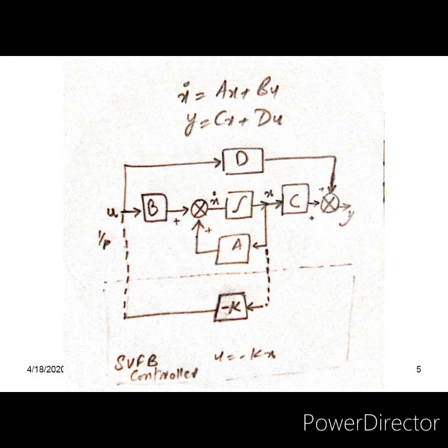It is actually the implementation of this state equation, because we have a plus sign at the derivative of x in the state equation. Derivative of x is equal to ax plus bu. There is no negative sign here. Therefore the first summer, the summer on the left hand side, should not contain any negative sign. Don't confuse it with the negative feedback as such. That is something else. Negative feedback is there in the system. We'll talk about it just in a moment.